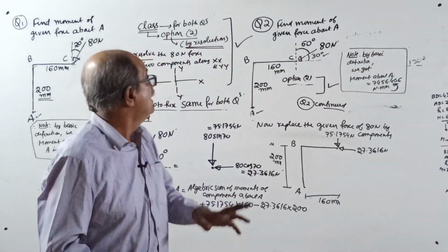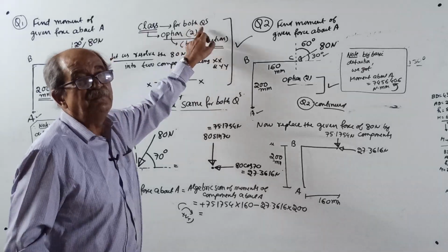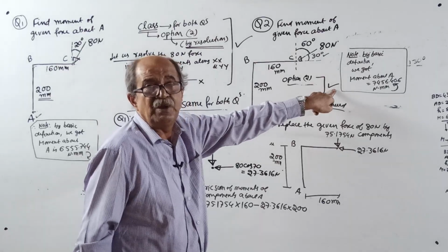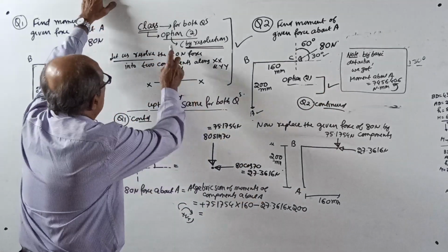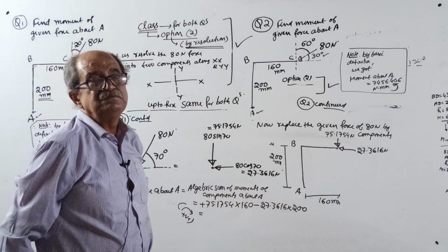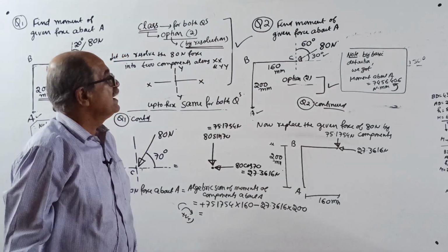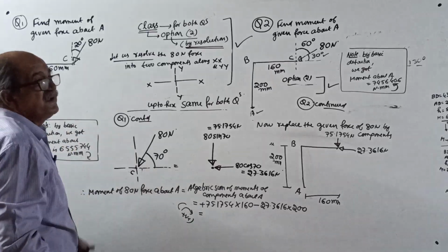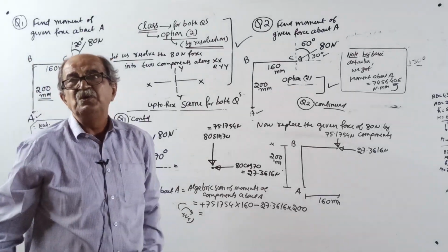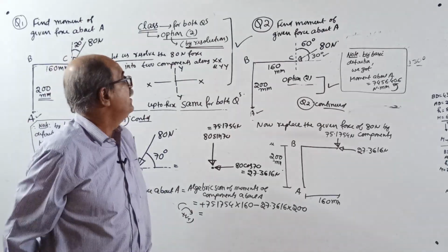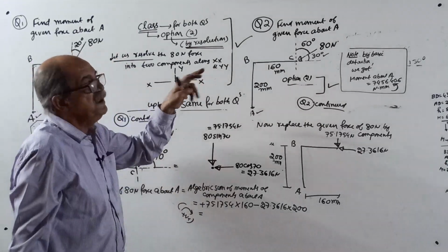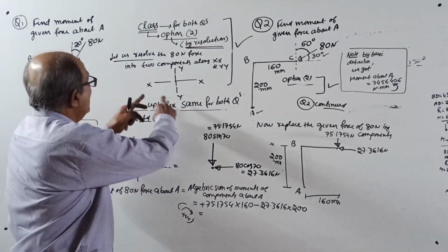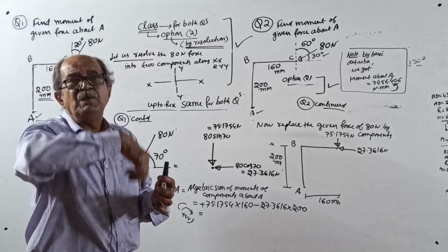Start. Now, class, I am dictating something for both the questions. You should write here, see, the right mark. The same right mark is required there also, if you are serious. Option 2, by resolution. Instead of struggling with all that force acting here, where it will cut, the perpendicular distance, etc., you can get the answer very, very easily by replacing the given force of 80 Newton by its components, one in the horizontal direction, say x, the other in the vertical direction, say y, right here.